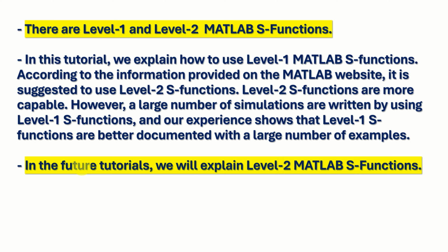There are level 1 and level 2 MATLAB S-functions. In this tutorial, we explain how to use level 1 MATLAB S-functions. According to the information provided on the MATLAB website, it is suggested to use level 2 S-functions. Level 2 S-functions are more capable. However, a large number of simulations are written by using level 1 S-functions, and our experience shows that level 1 S-functions are better documented with a large number of examples that can be found online.